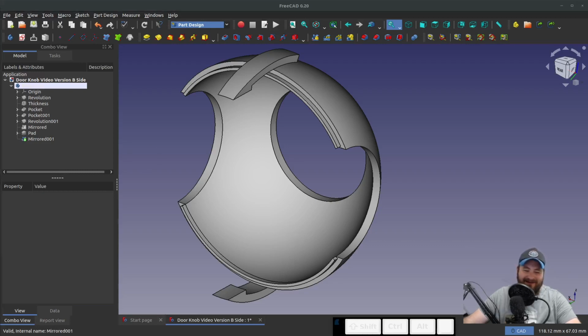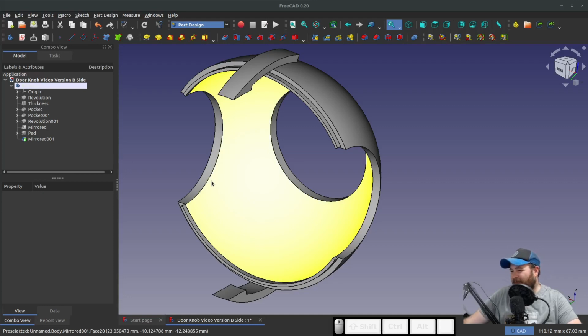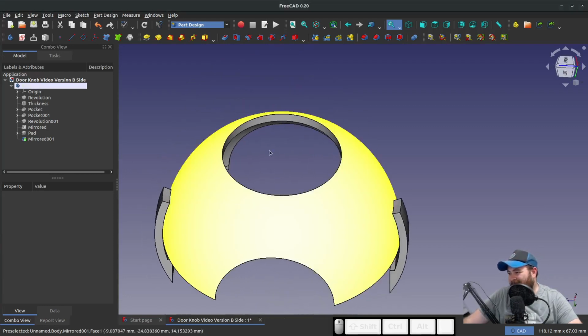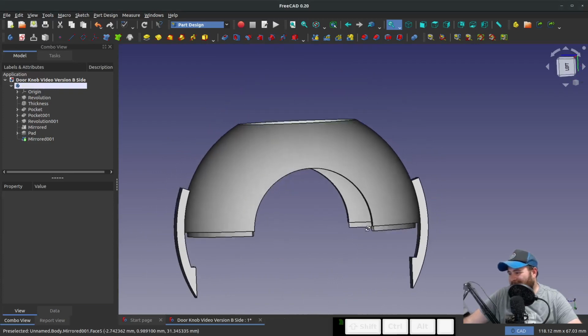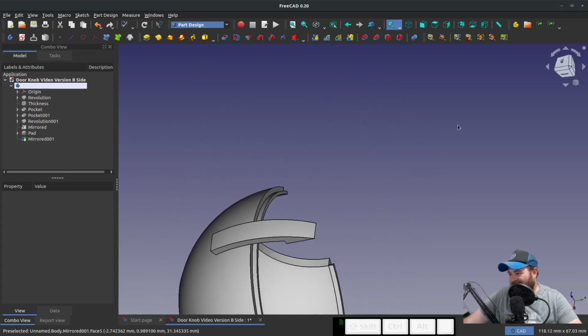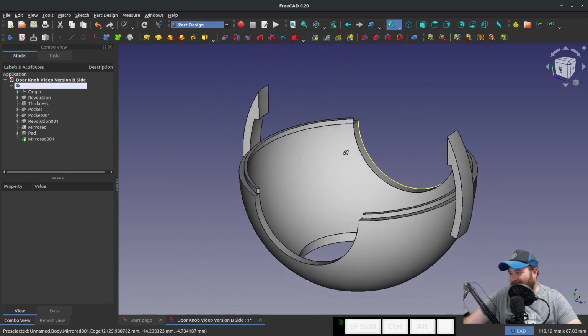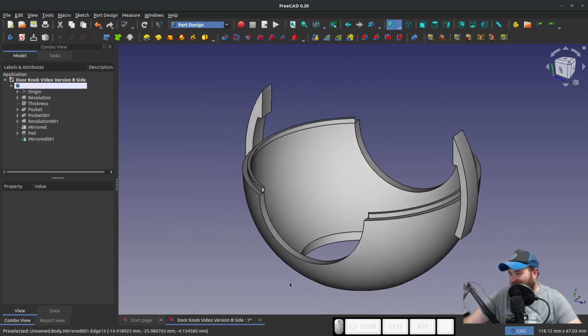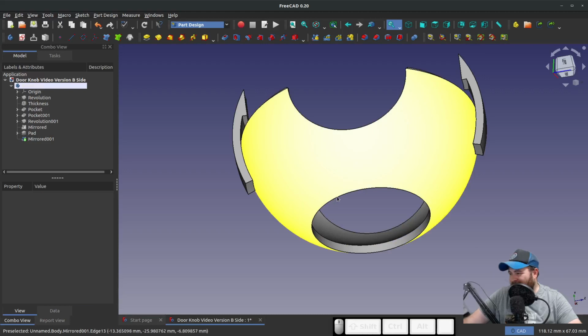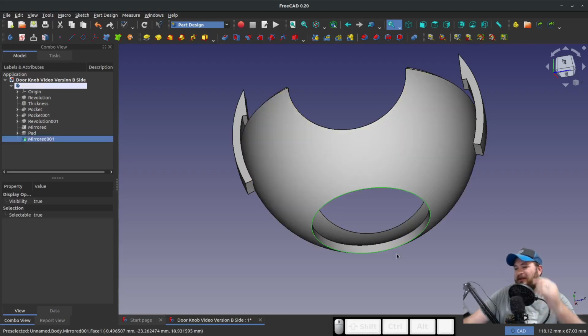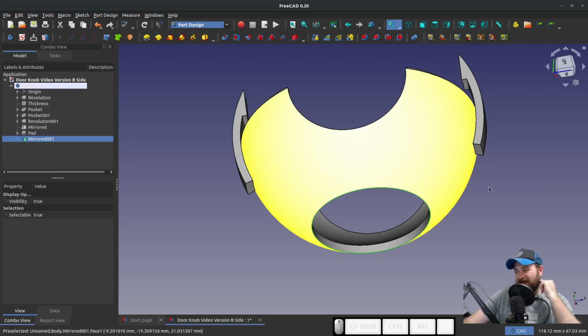All right. Finally, again, we want to give thought to how we're going to orient this for printing, and orienting it this way with the print bed down here doesn't make much sense. Sideways would also be a difficult print. I think our best bet is to orient it like this with the print bed down here. We have a little knife point right there, so we probably want to make some modifications to have some better bed adhesion. You can also use a raft, all right?